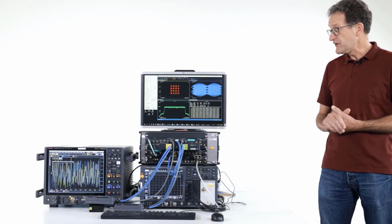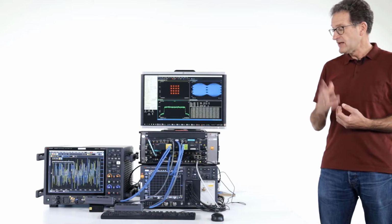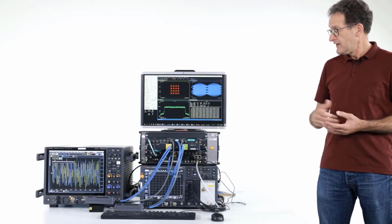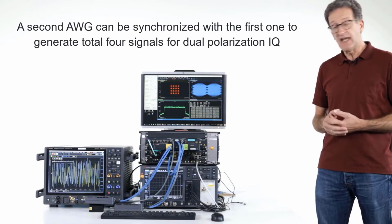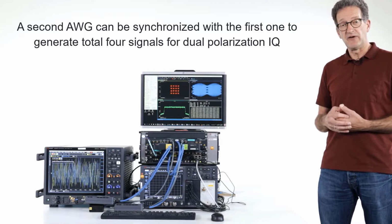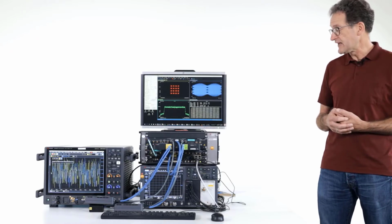So in this configuration, we can use the 2 channels of the AWG with a bandwidth of about 70 gigahertz to generate 1 IQ pair of signals up to roughly 140 GBaud. For dual polarization experiments, we can add a second AWG module that is synchronized with the first one, and that allows us to generate a second pair of IQ signals so that we can generate a total of 4 signals for dual polarization IQ.